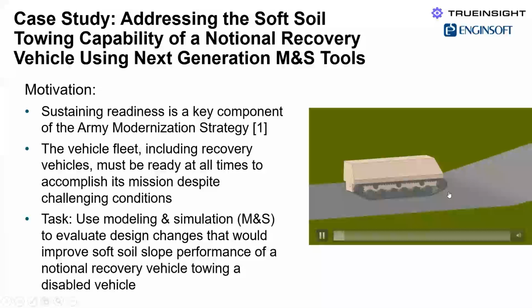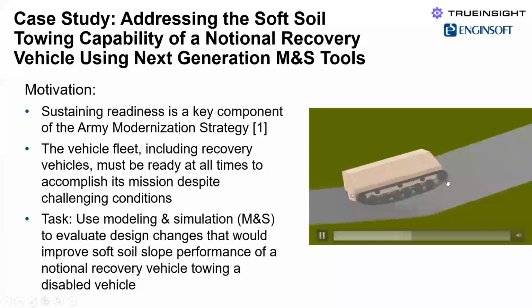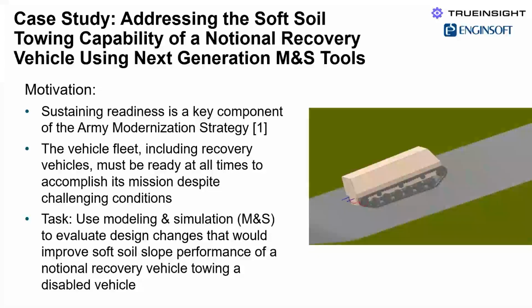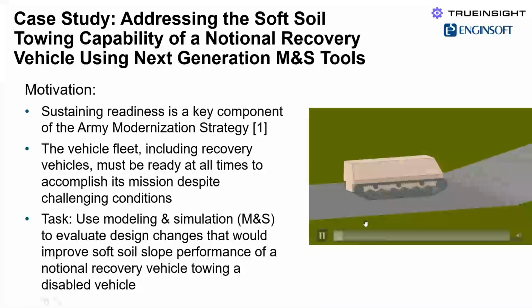And then at some point, as we increase the resisting loads, the vehicle will not be able to continue to proceed, and that tells us what the capability of the vehicle is as far as what it can tow up that slope. So why is this being looked at?